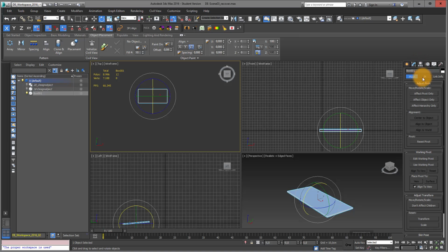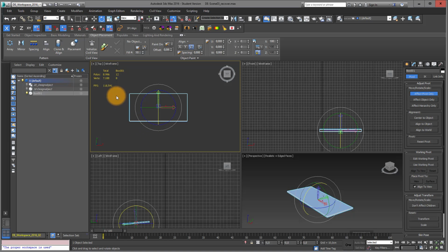In this menu hierarchy there's something like effect pivot point, and if you switch this on and move into my top view, then you can move the pivot point. By the way, also something which you could get used to, there are shortcuts like Q, W, E and R, and you can see what happens if I go through these letters. You can choose your transformation tools. So if I go into E or into W, you can move the pivot point to the top.